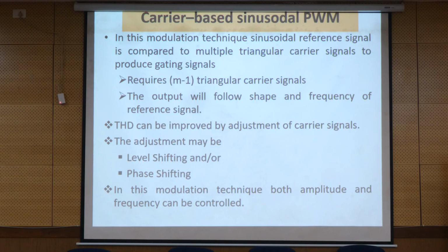In this carrier based PWM modulation technique, a sinusoidal reference signal is compared to multiple triangular carrier signals to produce the gating signal. It requires m-1 triangular carrier signals.